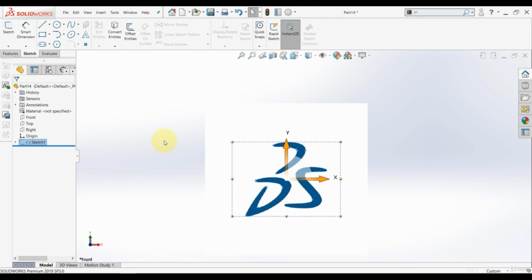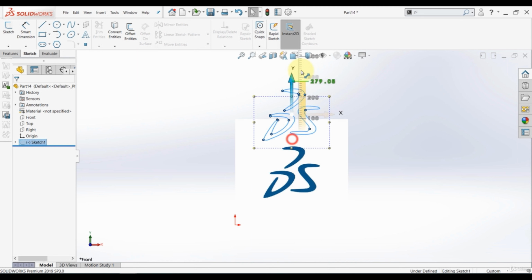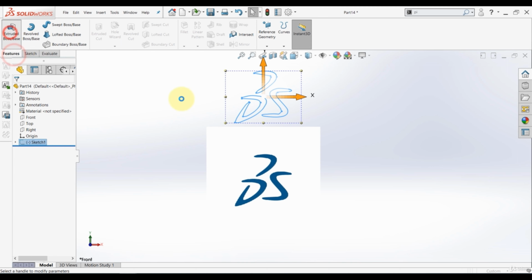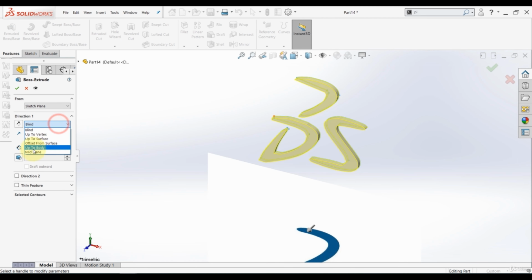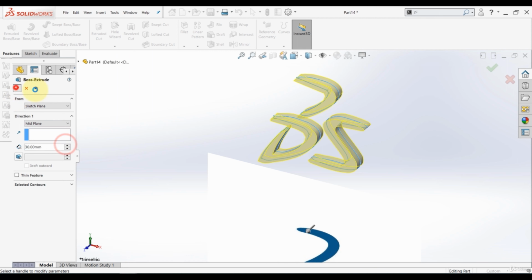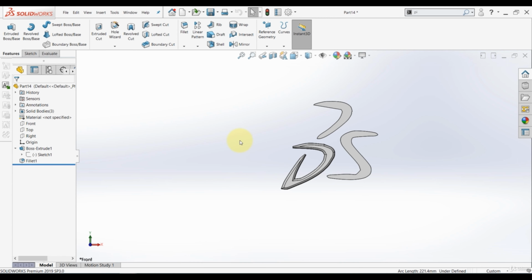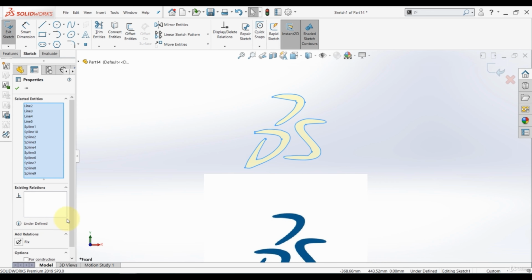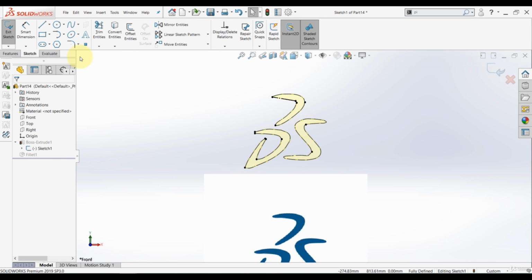Finish it. And let me show you an example of how this method can be beneficial. I'll drag this here. And now I'll select this sketch and select Extrude. And we can have a 3D geometry out of this. Now you have the option to use that sketch directly, or simply you can modify that sketch. So if I choose all of these and set them to be a construction geometry, and now I'll select it again and I will set it to be fixed so it won't move, I can snap to it and use it in my new sketch.